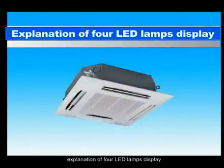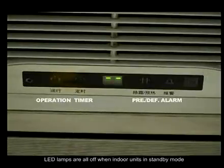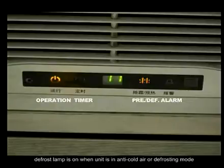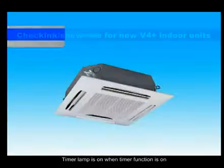Explanation of 4 LED lamps display. LED lamps flash slowly when power is on. LED lamps are all off when indoor units are in standby mode. Operation LED lamp is on when unit starts running. Defrost lamp is on when unit is in anti-cold air or defrosting mode. Timer lamp is on when timer function is on.